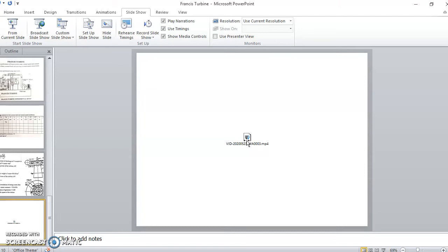Due to this, the speed of the turbine will decrease, and we should get back to the original speed of the turbine by adjusting the gate valve or the guide wheel. And we should note down the readings on the pressure gauge, vacuum gauge, time for n revolutions of the energy meter disc, and head over the V notch. And we should repeat the steps for different load conditions, and make sure that the load is released before switching off the turbine. These are the general steps which we follow to get the experimental values of the turbine at constant speed.